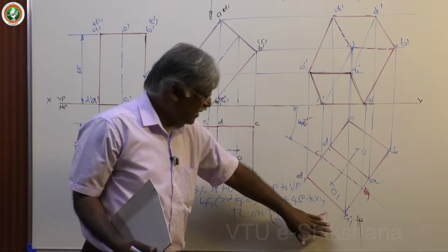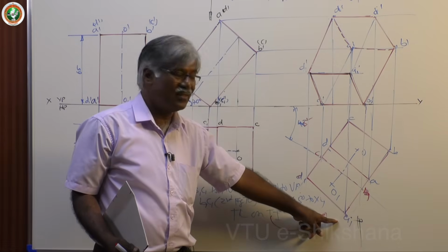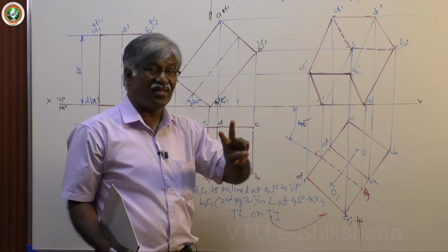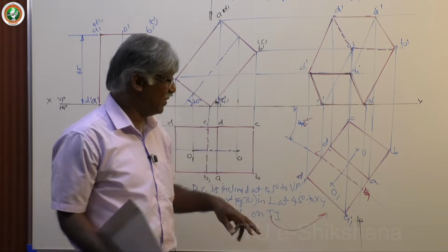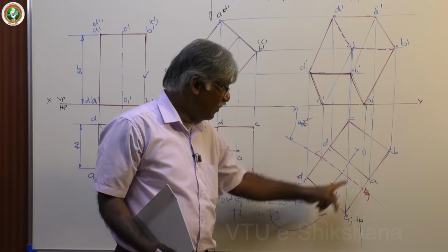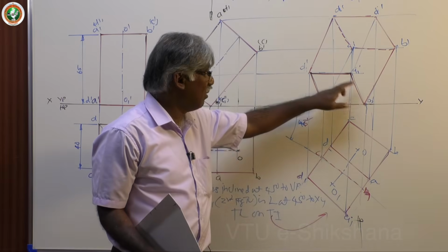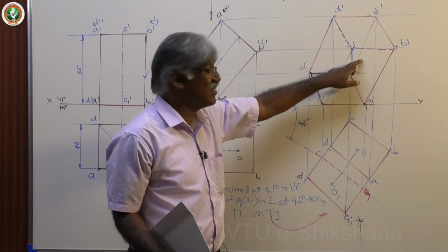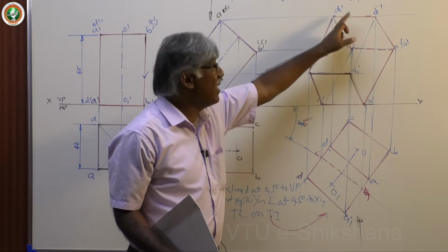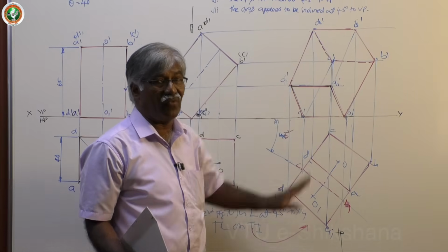So I have completed three basic procedures. One is visible key surface. Since I have two key surfaces in a prism, in case of a pyramid we have only one. I will tell you what to do. Easier. We have two key surfaces. Visible key surface dark, all edges. Then boundary lines dark. Then invisible key surface lines other than boundary lines are not visible. Boundary lines always visible, that we have fixed.